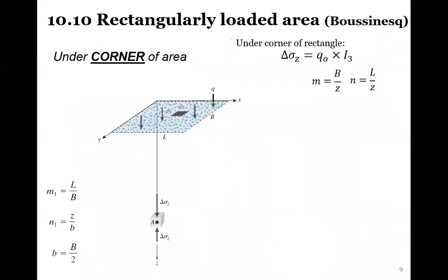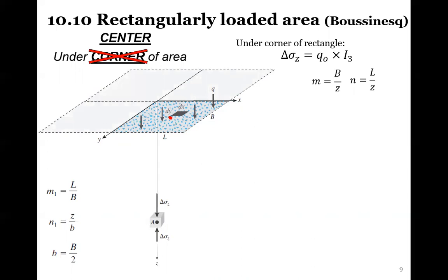So the interesting thing is, this area of the corner, we can actually use to determine the area of the center of it, as most of the time, that's where we would assume the larger amount of loading is going to be. So although the math is all derived for the corner, all we need to do is assume that there are 4 areas surrounding it. And now if we analyze each area in the corner, that then becomes the center.